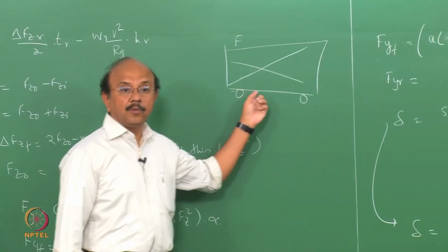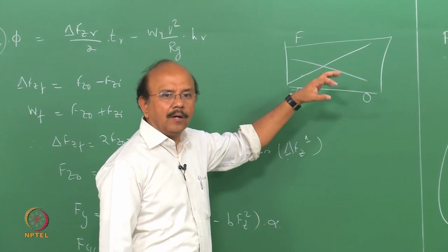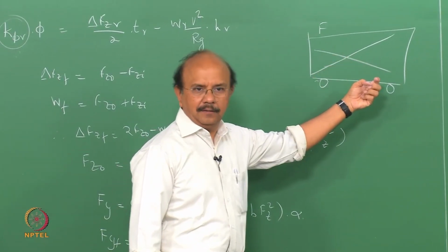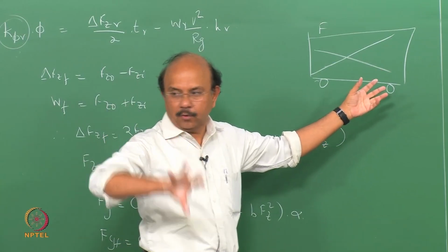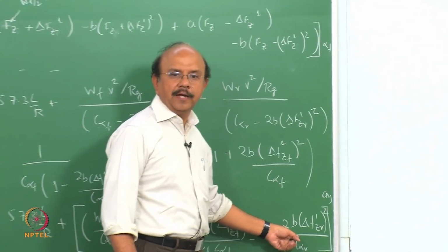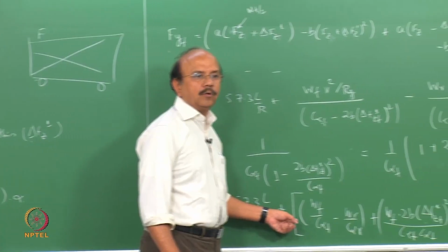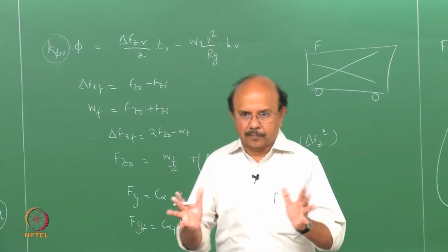If nose down, the roll would produce more delta Fz in the rear, right? Because the height, that's what causes the roll. So which means that this guy is going to be higher, and so the vehicle is going to be more oversteer. Okay, so this is how you interpret it.